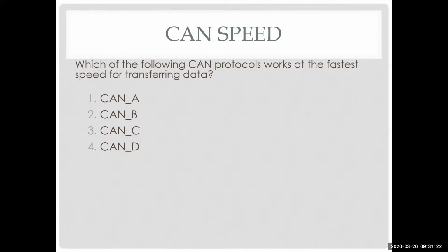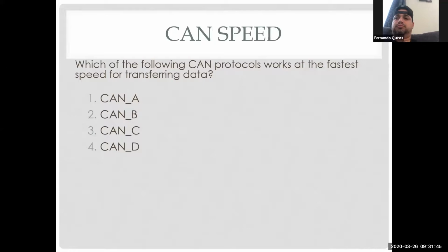So, Brian, what's the difference between B-CAN and CAN-B, or is it the same thing? Sometimes manufacturers will call it a B-CAN as being a second CAN, or like I was talking about, Mercedes calls it a B-CAN, meaning body CAN, not talking about the speed, where CAN-B is the speed. So some manufacturers really blur these lines. They don't stay consistent with the naming.